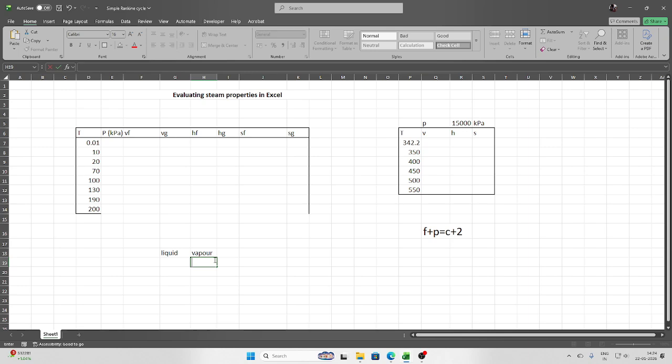Okay. Now this is for two phase, because in two phases only one independent property will be there. If you see the Gibbs phase rule, it says that F plus P is C plus 2. So for two phase substances, that means a liquid vapor mixture, let's say, P will be 2 phases, and the number of components will always be one, that is H2O.